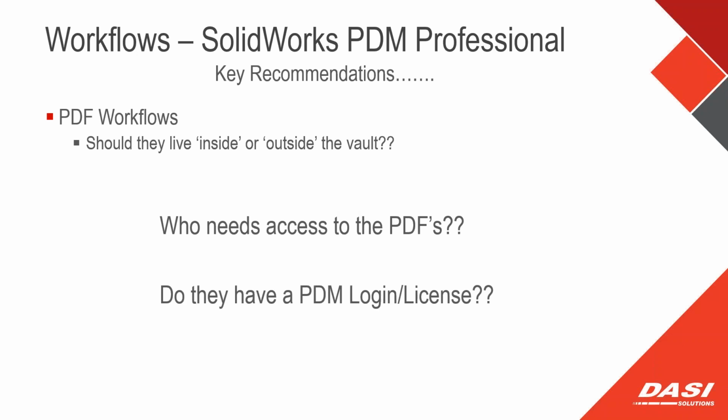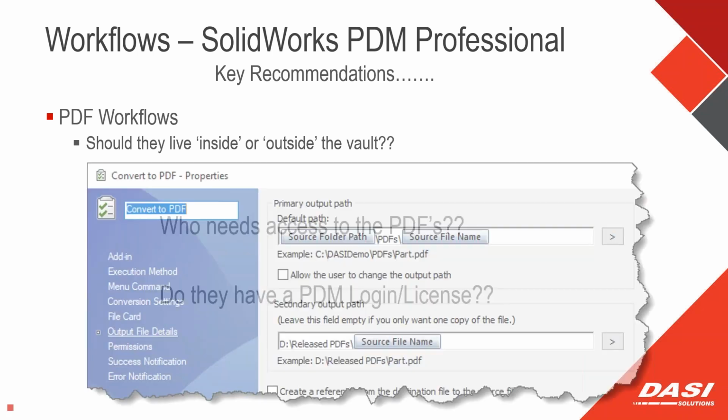And most importantly, do they have a login to PDM? Because if the PDFs live inside the vault and people can't log in, then of course there's a wall between them. Now, in a network environment, in most cases, a multi-user environment, we have a lot of licenses available, and it's only about the number of people that are logged into the vault simultaneously. So with viewer licenses, we try to foster access to the vault because it's the secure location, and that way you can take PDFs both in and out of circulation when they update. But if we're trying to mitigate license purchase just for the sake of cost mitigation, then having those files thrown outside the vault is definitely an acceptable practice.